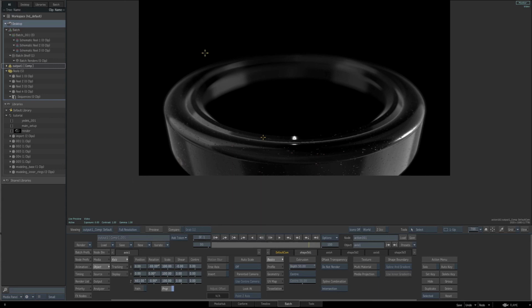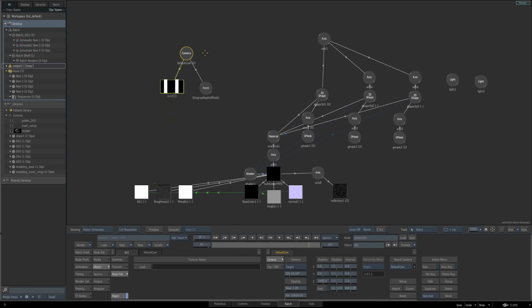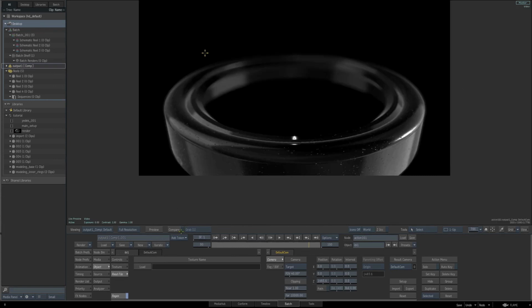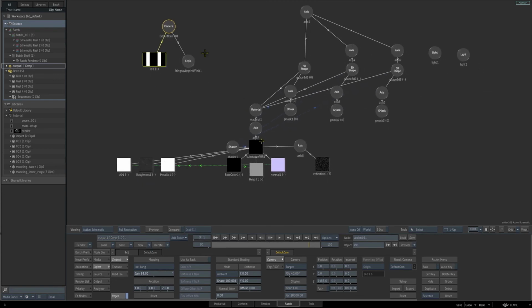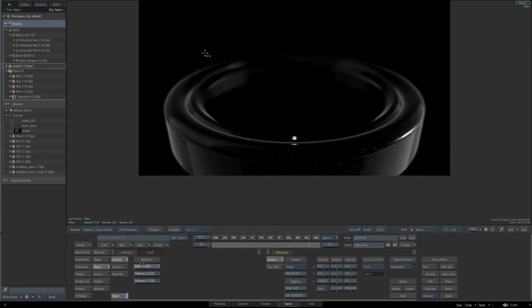If you want to control the lights that are on this shape, go back to our action schematic and select the image we're using on our IBL. And then down in the parameter settings, go to the controls for this IBL, and you can see the gain value that we can start to adjust. By increasing or decreasing it, we see the effect of the IBL light on our geometry. Or we can go back into the schematic and select our reflection texture once again. Go back to our end result, and now we have the effects slider that we can start to adjust.